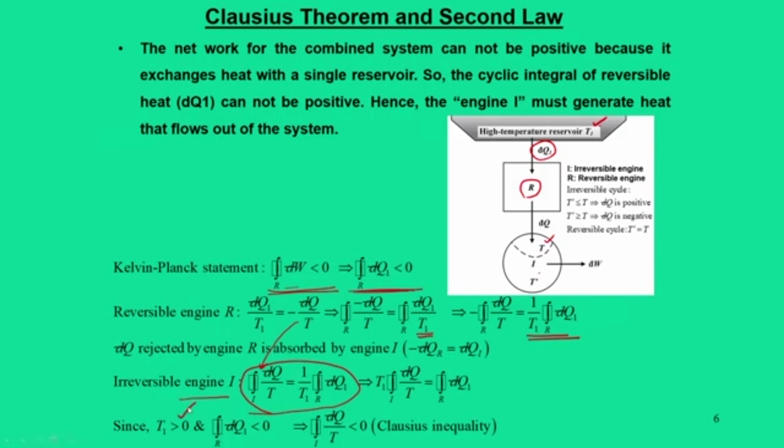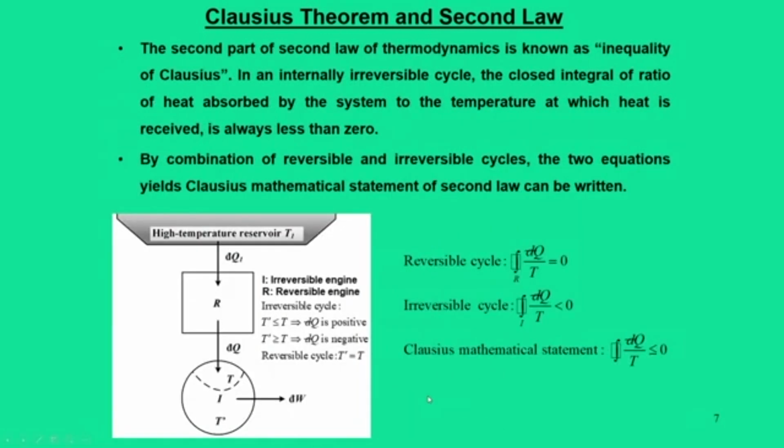So, if the process is reversible and isentropic, it means ds is 0, and ds equal to dq equal to 0 means this process is adiabatic, because now the process is isentropic and adiabatic. Isentropic means ds is 0, adiabatic means dq is 0, then it has to be reversible. In other words, we can write isentropic adiabatic can be reversible, or isentropic adiabatic irreversible. In a simple sense, we normally refer to isentropic process as the same as reversible adiabatic process.